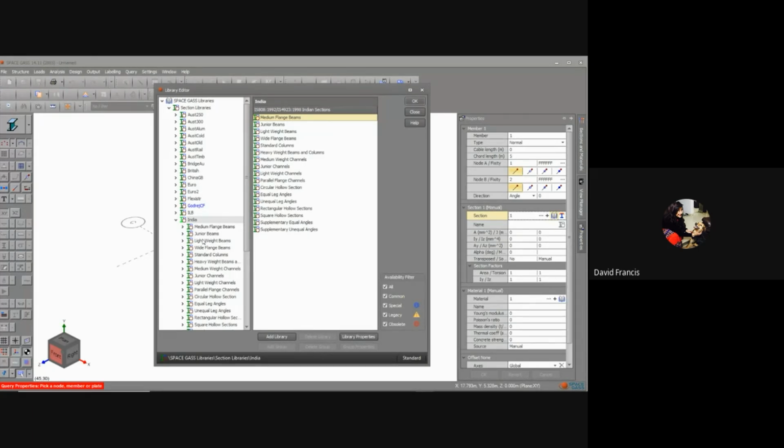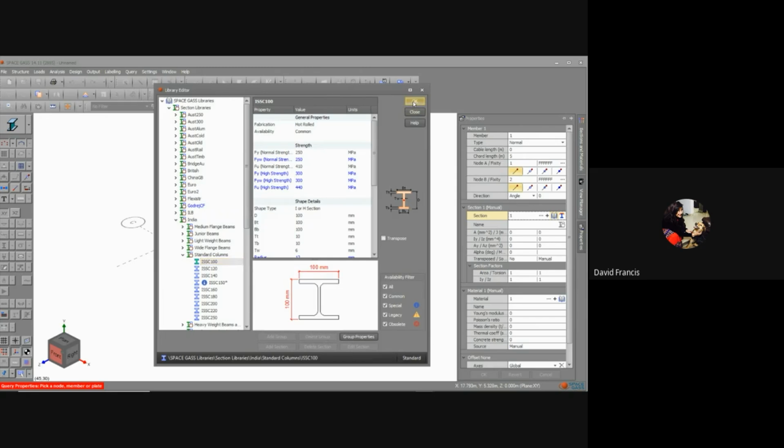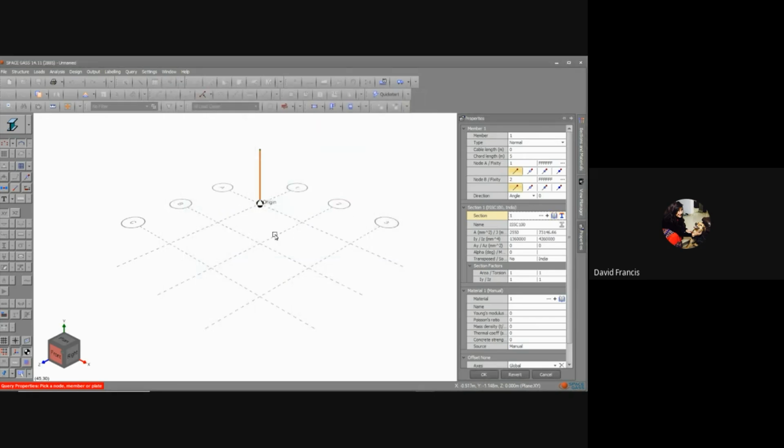We don't have time in these workshops for the seismic checks as well, because there are seismic checks which are separate. They have very specific load cases, and the design checks are slightly different. And they include things like web to flange ratios. So the sections that we use become quite important. So I'm new at work, and I've decided to start off with a standard column, and I've chosen the very weakest section I can, because once again my focus at the moment is I'm trying to save in the weight of material. So this is a good workshop you can do with your students.